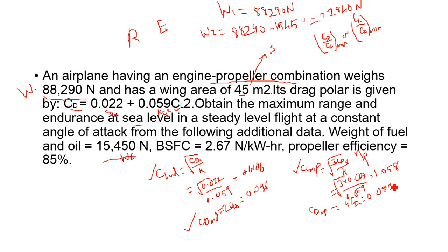Now we can substitute the value in CL by CD. Straight away, we can also put that in our range equation and break out the equation. So I will find it directly here. First, CD divided by CL is equal to, we will be getting the value like 0.0721,